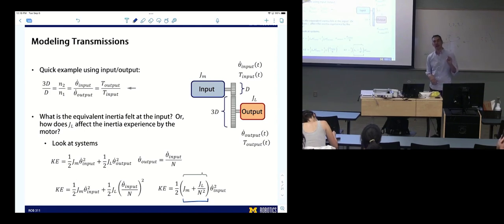Yeah, so that's a different concept, but a good point. So that concept, I think what you're saying is, maybe there are certain times where backdriving the system is not advantageous, and it would be more advantageous to have the system hold its position, sort of be locked without effort. Yeah. So there are types of transmissions that do that, which would be called non-backdrivable, where they can't run this direction, so physically impossible.